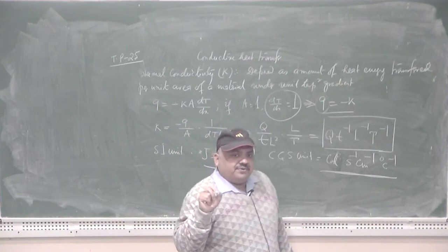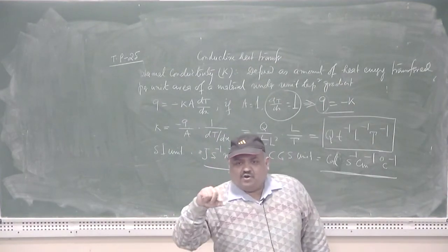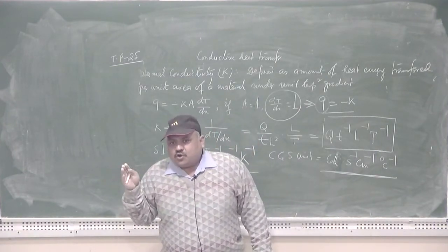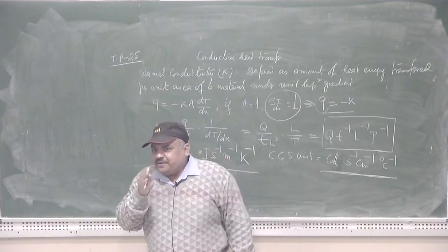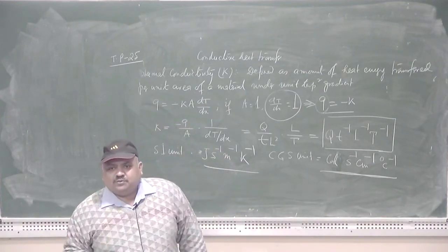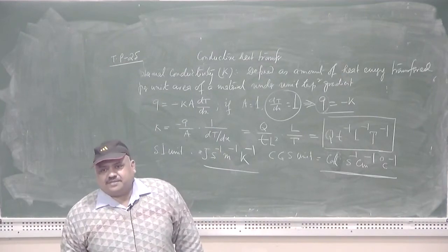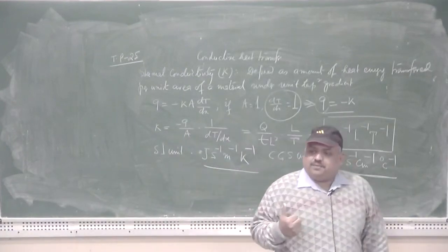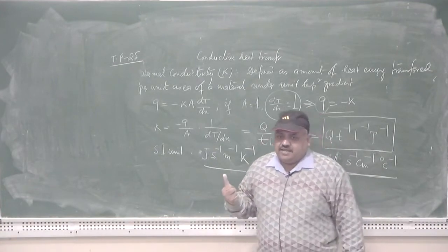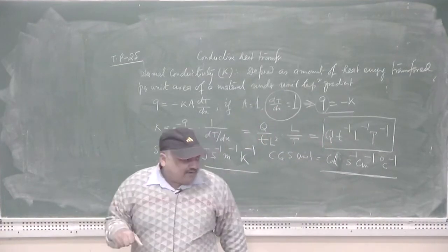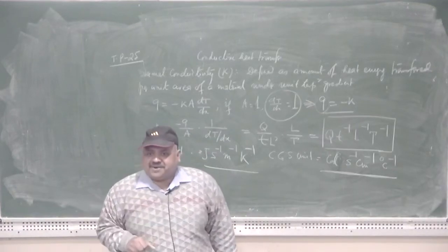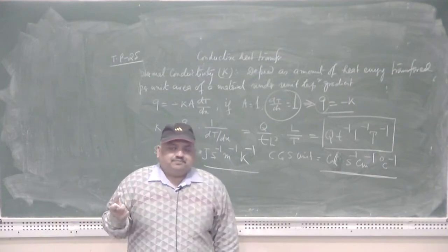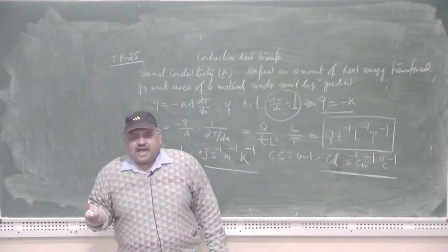If I consider a specific volume, and in that volume so many grains can be nucleated, then the space available for each nucleated grain will be confined to some extent. Under these circumstances, for metals or alloys solidified in the particular mold material, if the rate of nucleation is high, and as a result the growth rate can be suppressed or restricted, a finer grain in the microstructure may result. This gives rise to an enhancement in the mechanical property of the alloy.